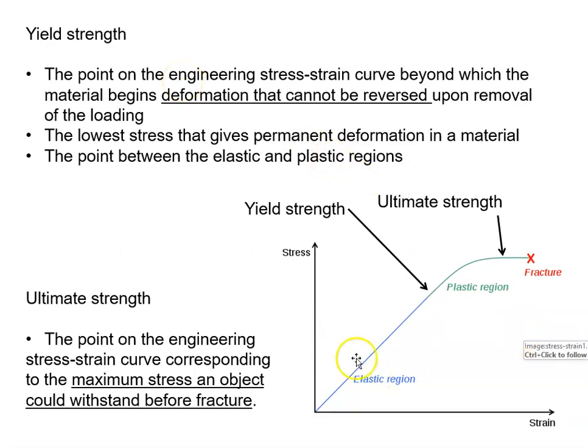All right, so now taking a closer look into the stress-strain curve. The yield strength is occurring right there. This is the blue elastic region, and then right here we have a change in color, and it goes into the green plastic region. So elastic, things snap back. Plastic is permanent deformation. This point is the change between elastic, where things are snapping back and everything's okay, and then right here, some permanent damage has occurred. Now when that load is taken off, it's not going to bounce back to the way it was. Some permanent damage has occurred.